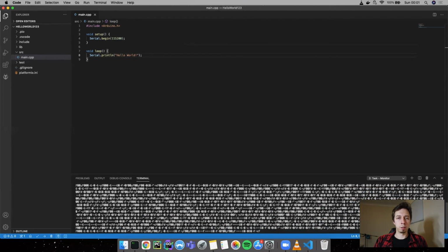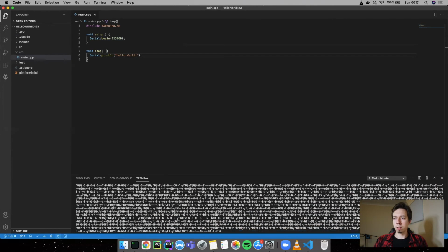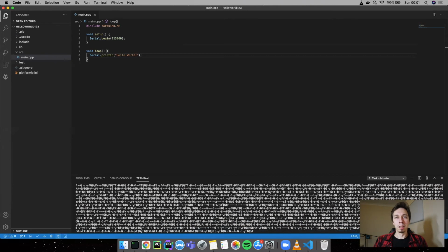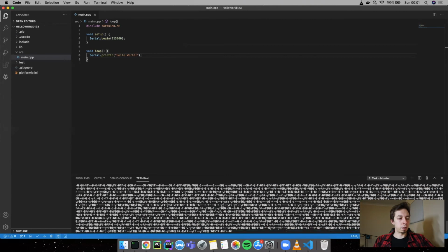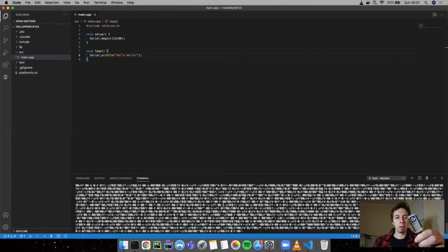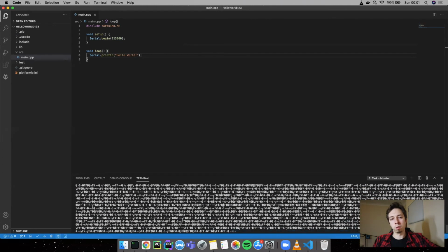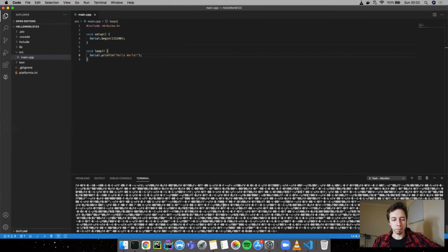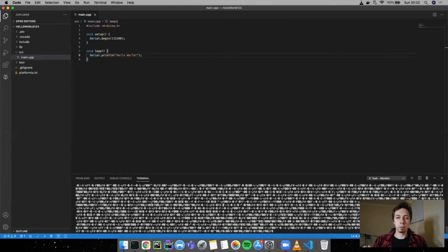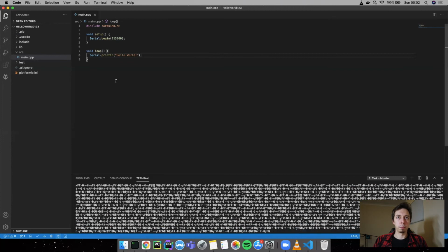But the format of this is not actually correct. I see that we're just getting some sort of information repeatedly, but this is definitely not hello world, right? The reason is that the device has a different default baud rate set. This is a very common issue with serial communication on ESP boards. And the fix for that with PlatformIO is very, very simple.